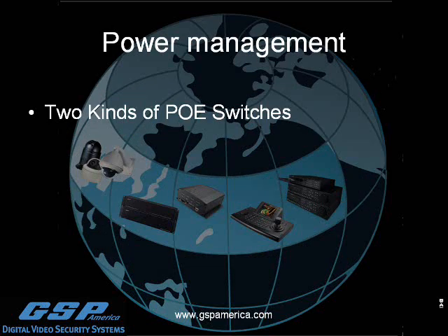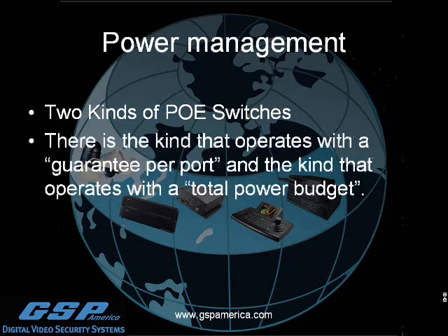So again, the second really big issue is what kind of POE switch do you have? There are two different kinds, and again, manufacturers have not been very good about advertising exactly what is in their device and what it does. The thing that you need to know is that there's the kind that operates with a guarantee per port, and there's the kind that operates with a total power budget.